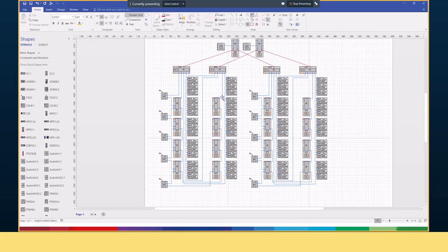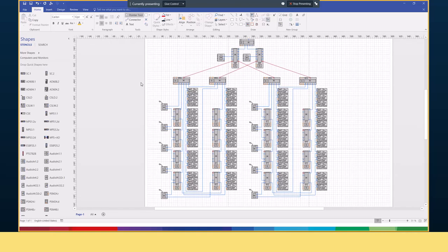But every time, the number of hops is always less than 22. And you know that you have to count the hops starting at the system controller. So the system controller is 1, the switch is 2, 3, 6, 9, 12, 15, 18, 19, 20. It's very close to the maximum. Yeah, so this is no problem. It's 20 hops, but don't go much higher. And you can see that for every loop that we've created. And on the right side, it's of course exactly the same.